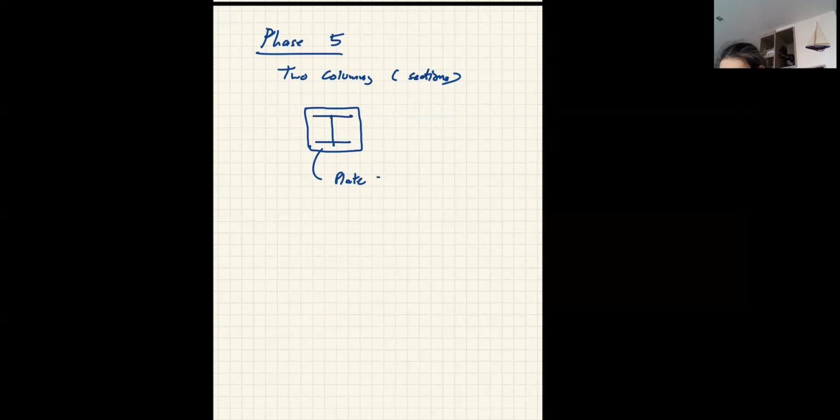Plate size must be larger than the column footprint, because you need to weld the column to the base plate. In order to do the welding, it has to be bigger. It doesn't matter if your required area is less, but you have to use the bigger physical size. Otherwise, it's impossible to do the real job.